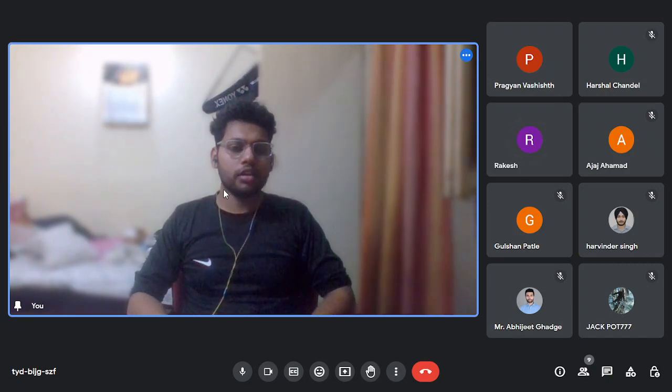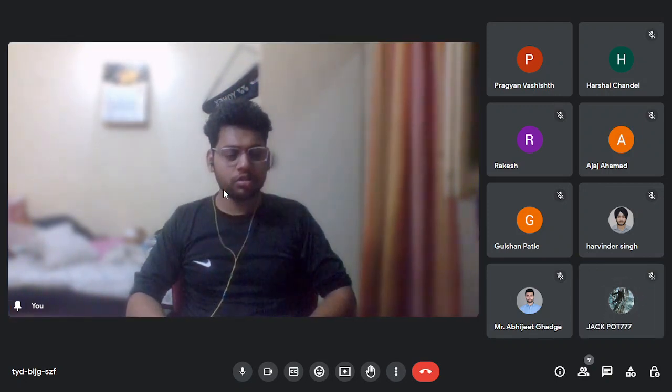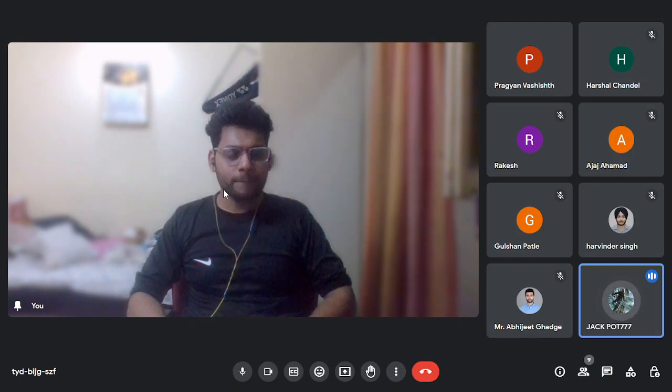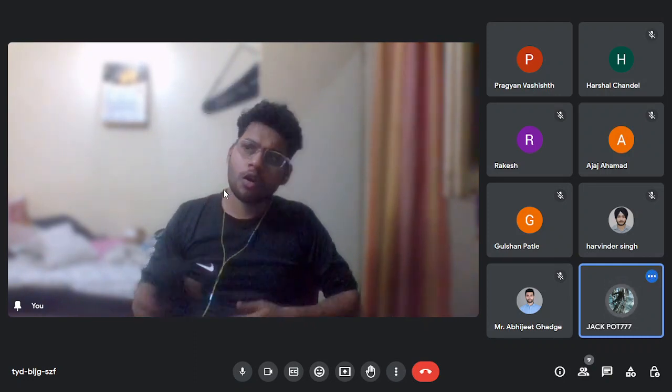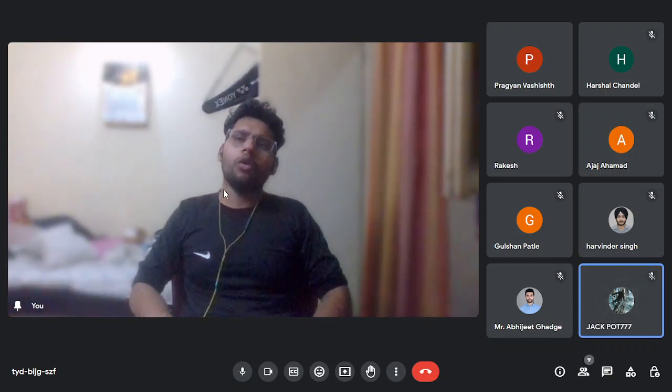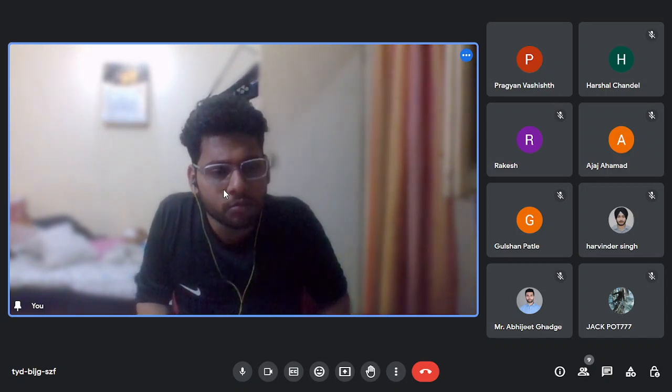My doubt is, on board ship, what do we have, fusible plug or low water level shutdown? Both. The fusible plug is a safety device, and low water level is a safety alarm and trip. The fusible plug is also a trip.